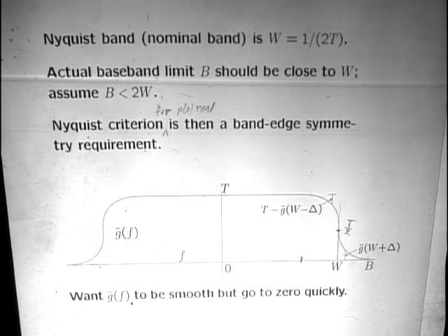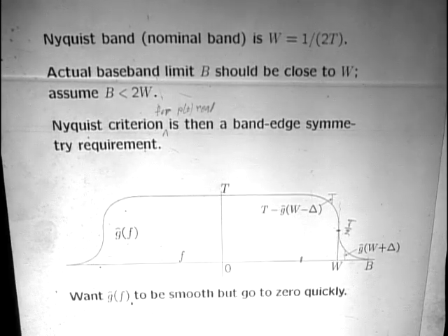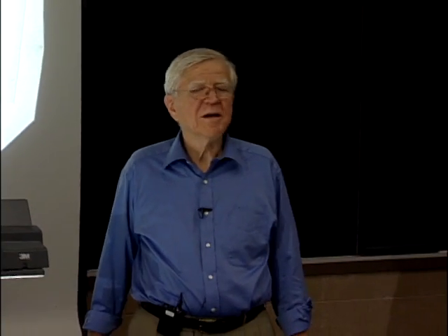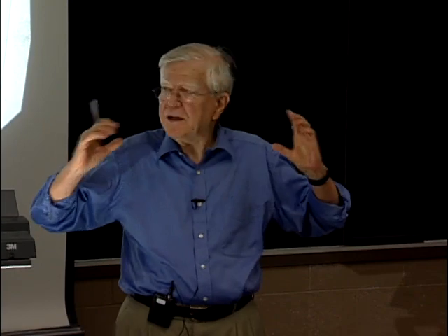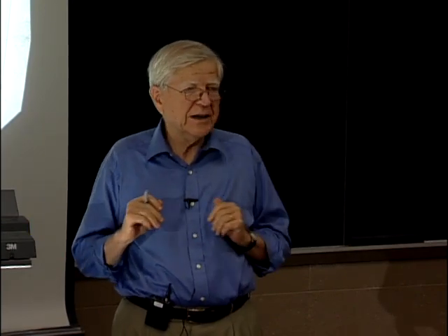The sinc pulse, because there's a discontinuity in the Fourier transform, can't go to 0 any faster than 1 over t. And something that goes to 0 as 1 over t goes to 0 very, very slowly. In other words, you have enormous problems over time, and you have enormous delay. And since you have so many pulses adding up together, everything has to be done extraordinarily carefully.